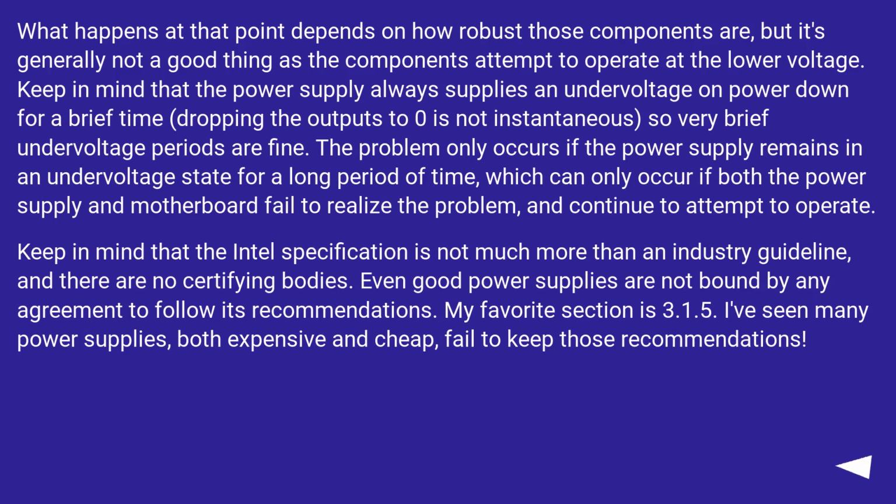What happens at that point depends on how robust those components are, but it's generally not a good thing as the components attempt to operate at the lower voltage. Keep in mind that the power supply always supplies an undervoltage on power down for a brief time. Dropping the outputs to zero is not instantaneous, so very brief undervoltage periods are fine. The problem only occurs if the power supply remains in an undervoltage state for a long period of time, which can only occur if both the power supply and motherboard fail to realize the problem and continue to attempt to operate.